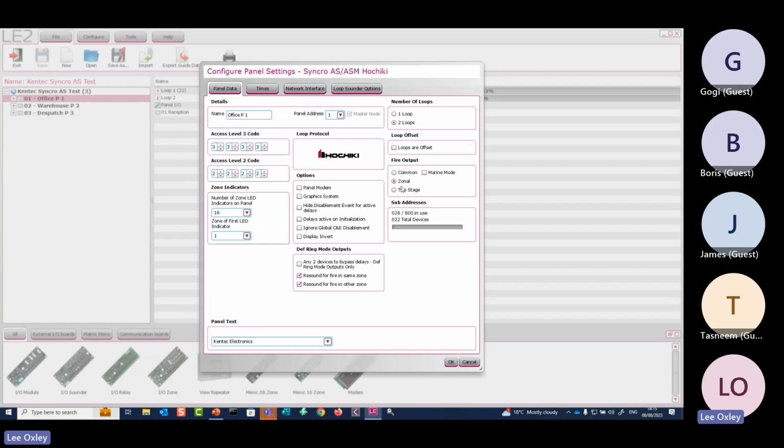Well, zone 5 will operate. All the sounders on the 5th floor would operate, and on the 1st, 2nd, 3rd, and 4th, 6, 7, 8, 9, 10 floors will be silent. That's just using that tick box. Did it 2-stage? Well, again, if zone 5 went into alarm, go continuous. So fully evac on zone 5, the 5th floor. All the other floors in the building will all go intermittent into alert mode.